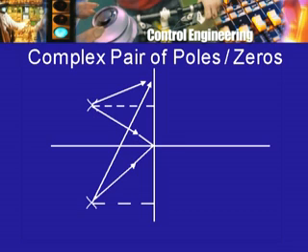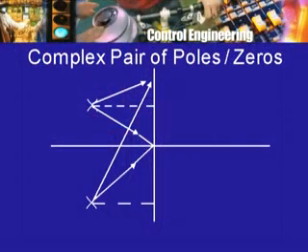So, when I have that, I have to plot a point here which corresponds to the corner frequency. For that, I have to find out what will be the net phase shift, and I will leave it to you to find out for yourself what is the phase shift corresponding to the corner frequency. And if you are about to be a good engineer, you can make a good guess as to what the phase shift will be at that corner frequency.